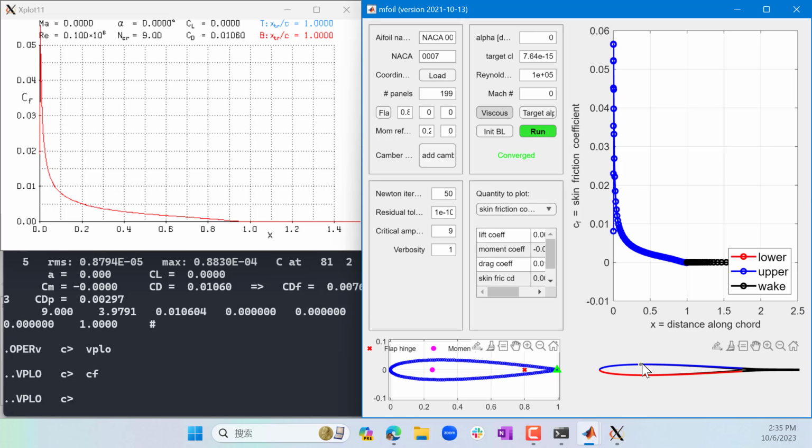Okay, so these point towards the right, except for at the very leading edge, which is a small fraction of the geometry, right? So they point in the drag direction, and the skin friction contributes very little to lift, even at non-zero angle of attack, because the skin friction points tangential to the surface, right? And the area over which the tangential direction has a significant vertical component is very small, okay? Right, very small.